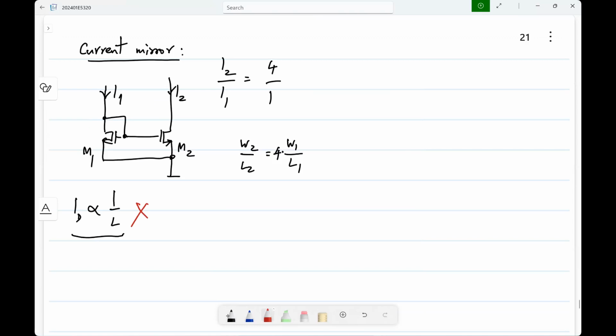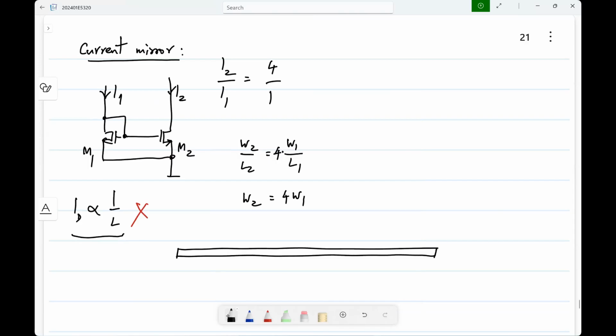That is, you can't make... for the same reasons that I outlined with the resistor, the ends will behave differently from the middle and so on. Not to mention, the layout becomes very unwieldy. Okay. So in a MOS transistor, you can have width that is very large. Okay. The length will be from a few nanometers. Okay. By the way, I did not mention this explicitly.